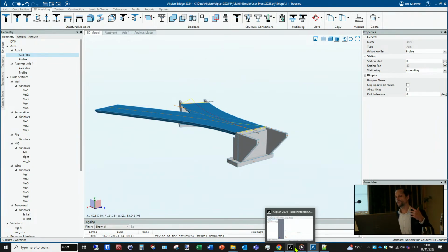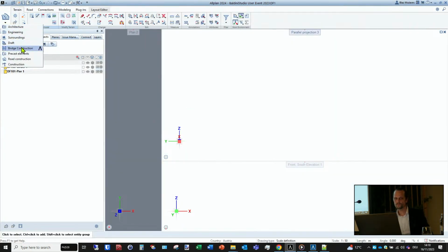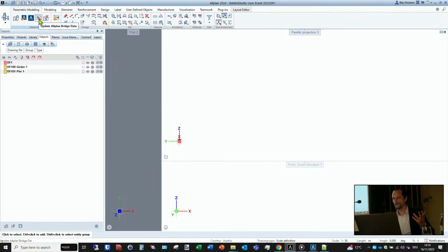And if, after we have created sections, we notice we still need some changes done in Bridge, you can still go back to Bridge and make the change. You then simply need to update your project in Allplan Engineering, and with the update you don't lose your work in engineering, and when the new model comes, all the sections will also be automatically adapted.